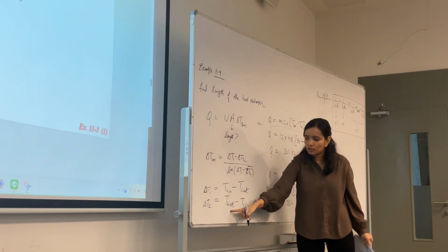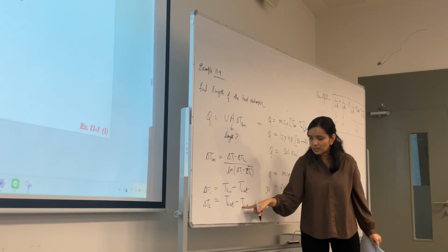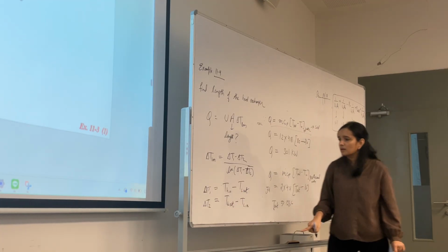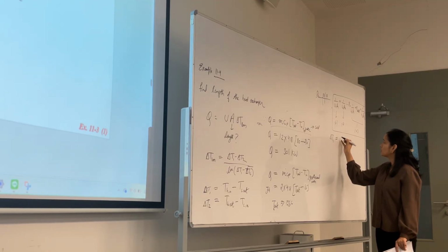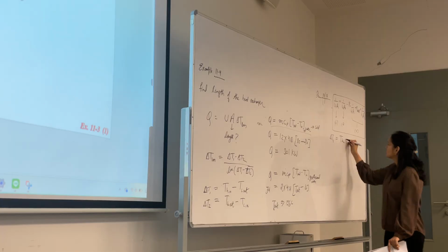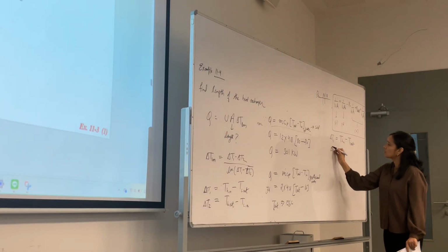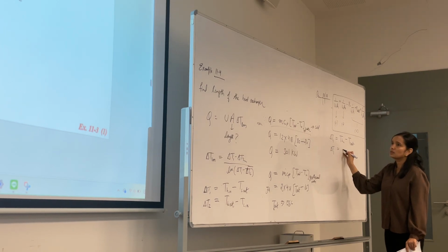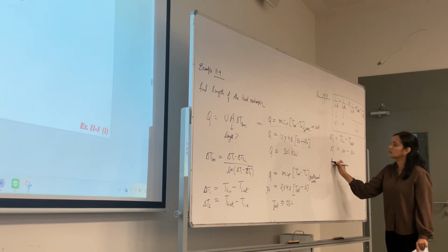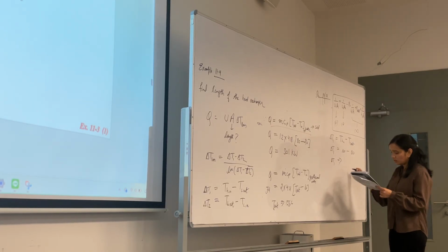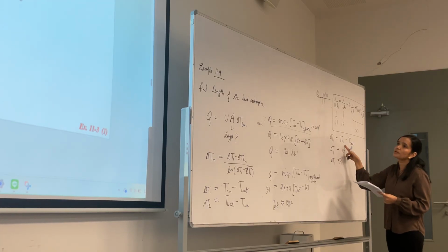So now we have this value. We have this value, we already had this value, and we have calculated this value. So we can now calculate ΔT1, which is hot in minus cold out. Hot in is 160, cold out is 80, right? Hot in.